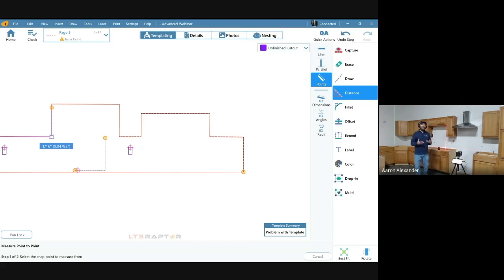So what dimensions can actually be affected by our reposition? Well, since we're shooting this line from position 2 and this line from position 1, these intersections here is where we can see this variance of dimension. So since we're shooting this line from position 1 and this from 2, we could see a variance in that number, a variance in this number, or a variance in this number, or this one. Okay, actually not this one. These 3 is where we could see that 16th in the accuracy of our reposition kind of show up on our tape measure here when we're checking this.